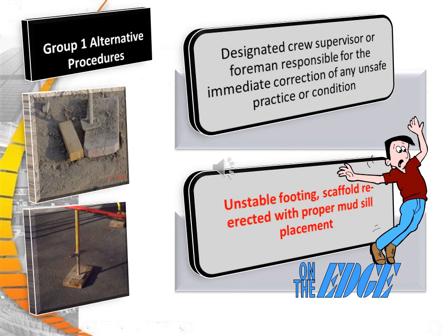A designated crew supervisor or foreman is responsible for the immediate correction of any unsafe practice or condition. Unstable footing, a scaffold re-erected without a proper mudsill, and improper ladder placement are all conditions that need to be corrected.